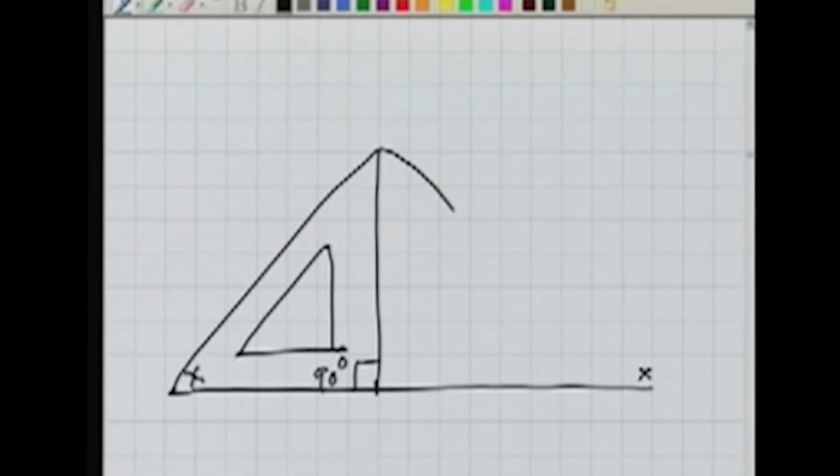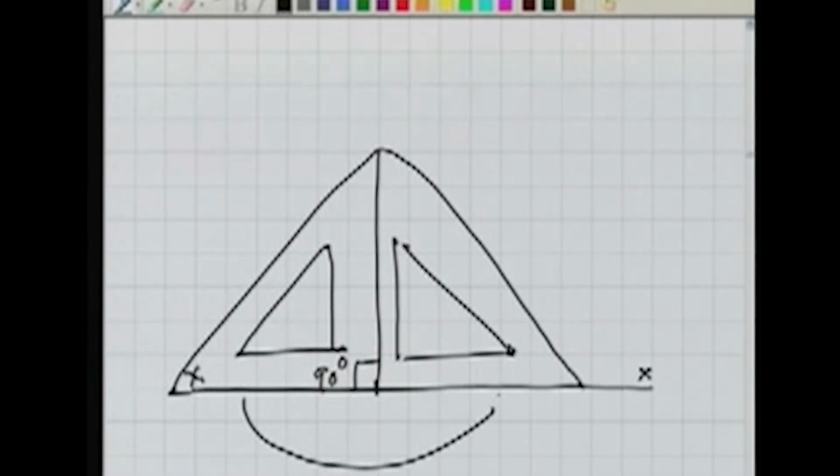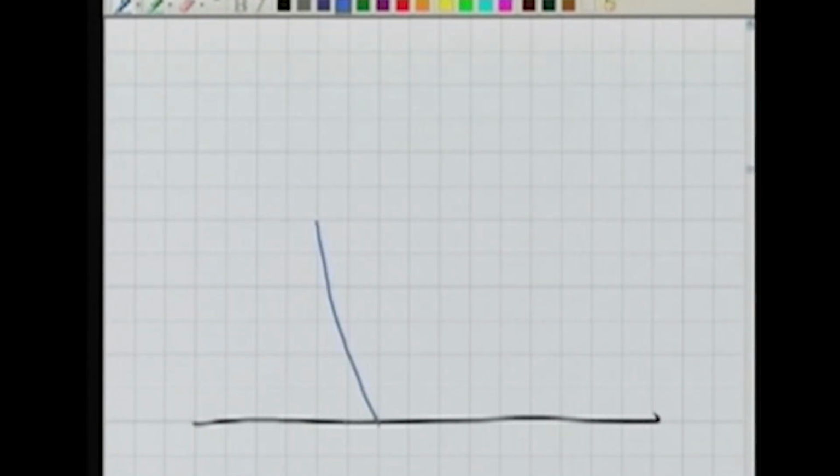So my set square will look like this. What I have done, I have just rotated it. Or other way around, we can say I keep this edge of the set square on this line and I draw a line. So these two lines will be same. However, if there is a problem, I keep my set square. Let us say there is error in the set square.